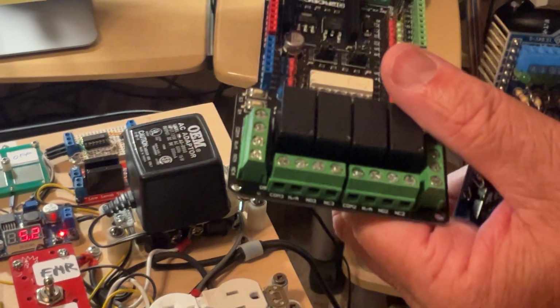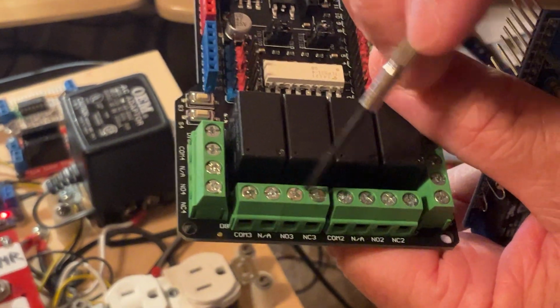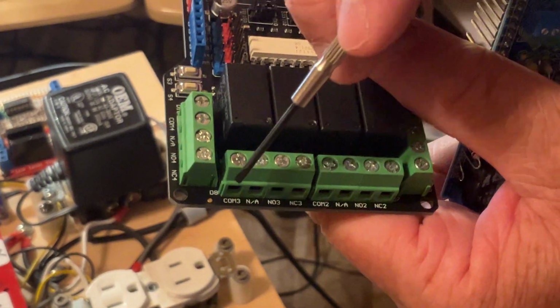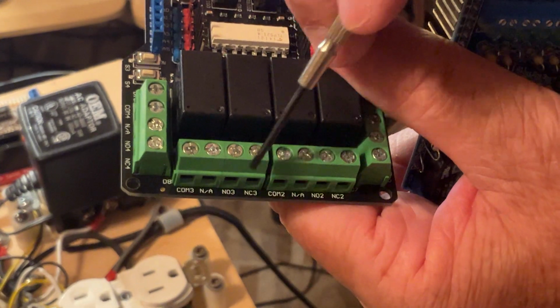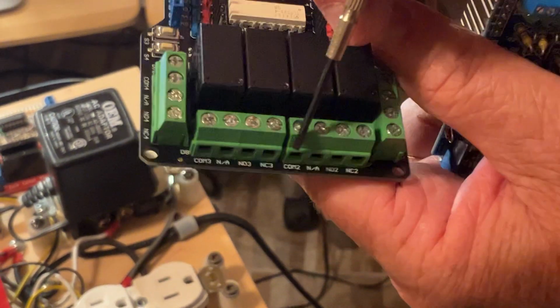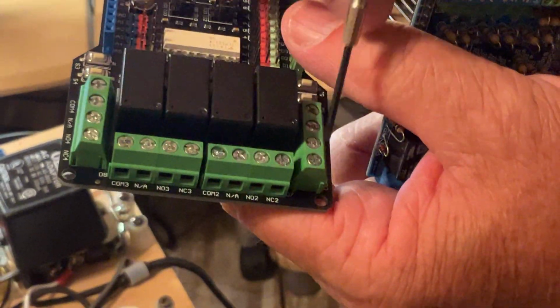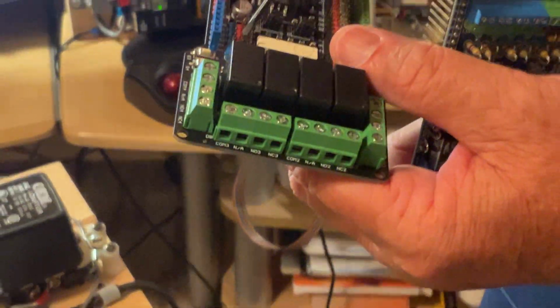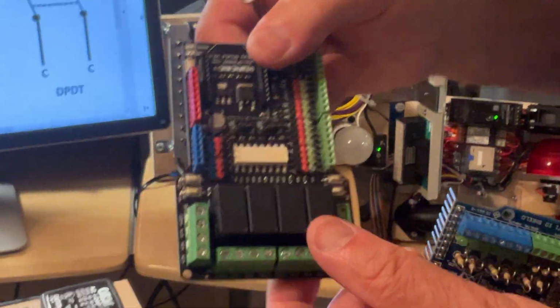And obviously, if you watch over here, it doesn't matter the terminal blocks, they have 4 contacts, one of them is not in use. You're going to find the common, and then you're going to find the normally open and the normally closed. Common, normally open, normally closed, and so on. Each terminal block has common, normally open, normally closed for each of the 4 relays. These ones are made to drive up to 3 amps, okay?